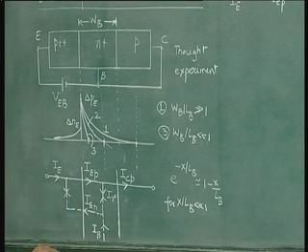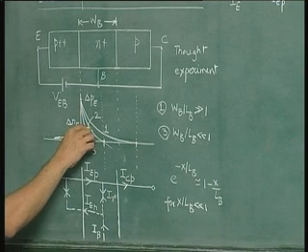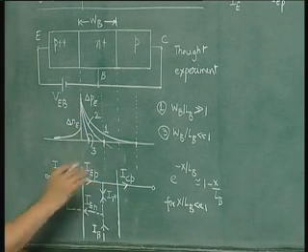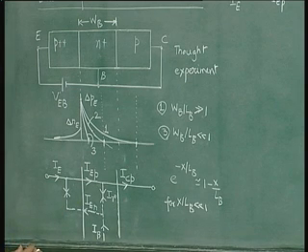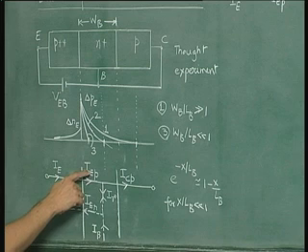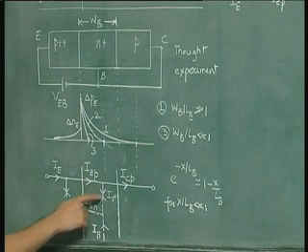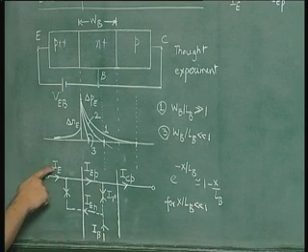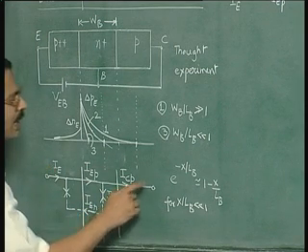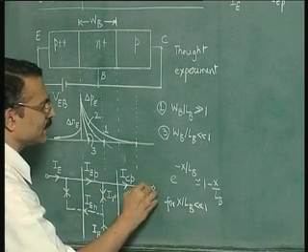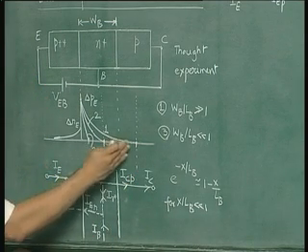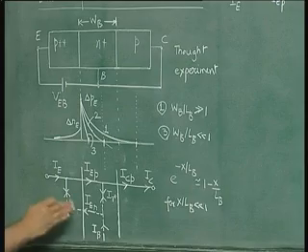In fact, it is the area under the excess carrier distribution divided by the lifetime in that region. We will see this in detail later. But for now, qualitatively we need to understand how the various current components IEP, IEN, IR and ICP, and therefore the emitter, the base and the collector currents, and the ICP here is the same as IC, change when you change the base width. That is the purpose of our analysis.